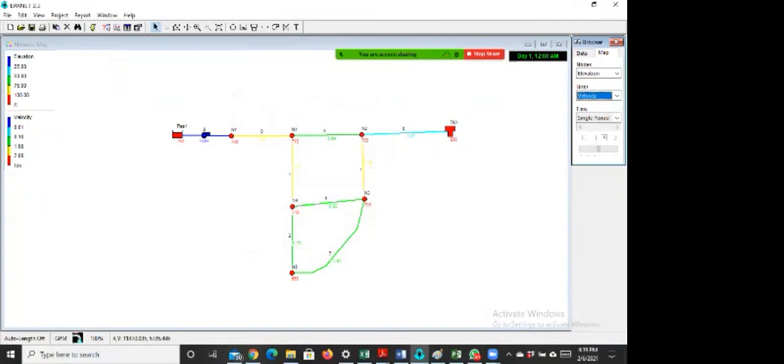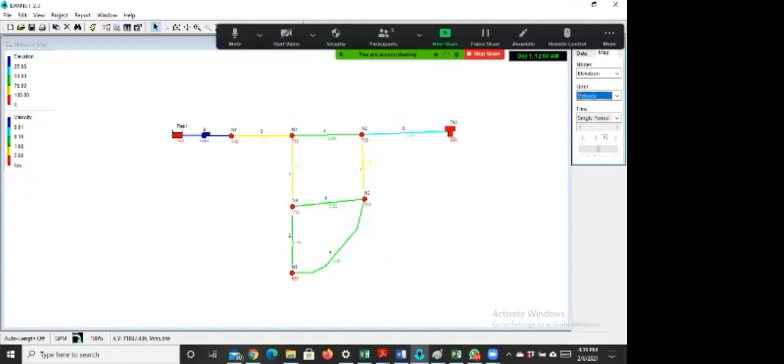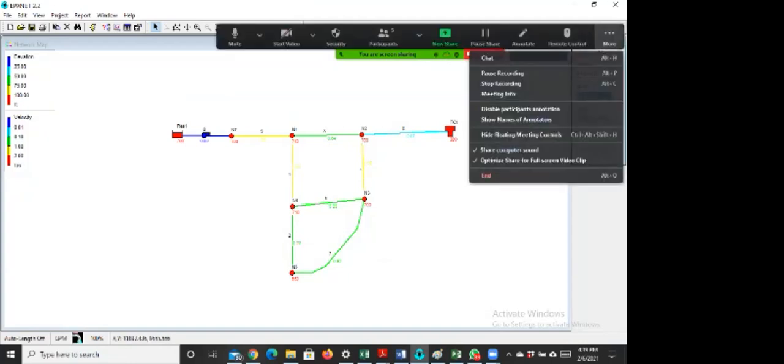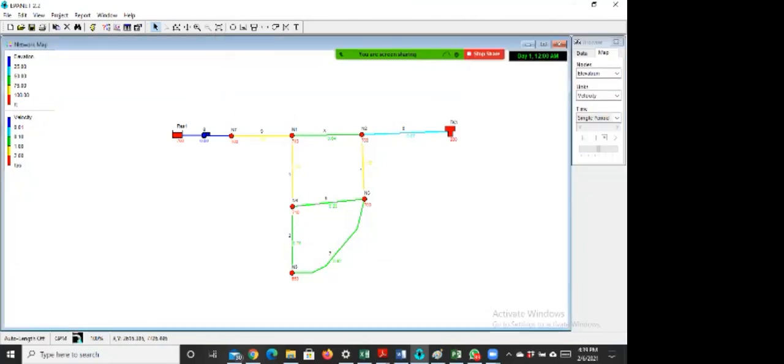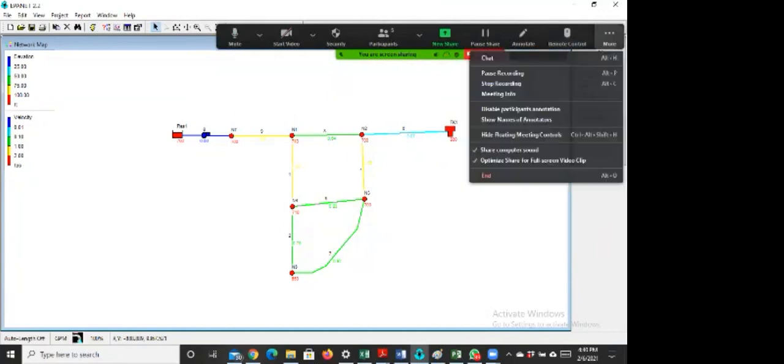So you can see that this is how you can design this simple network and run a 1 hour static analysis of what you have designed. So once again, you draw the network, you input the node parameters, you input the pipe parameters, you design the pump, you design the tank, then you run your analysis, and that is how it is done.